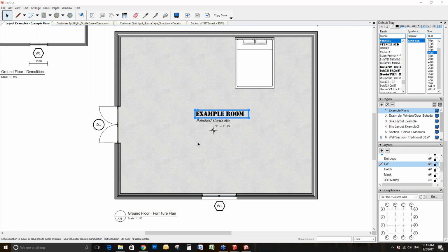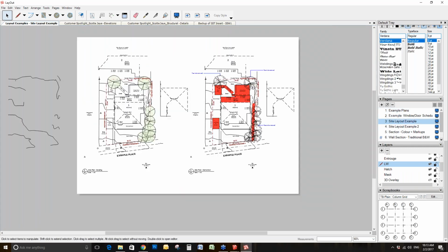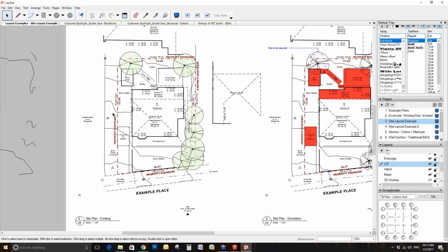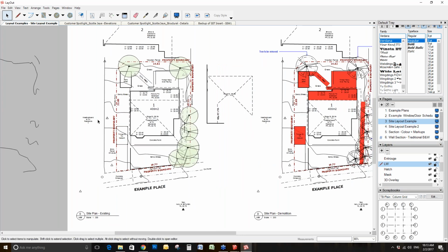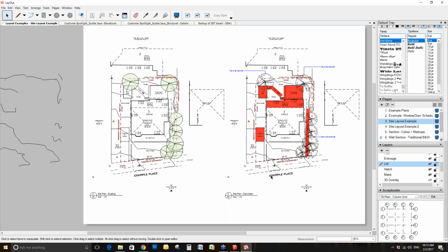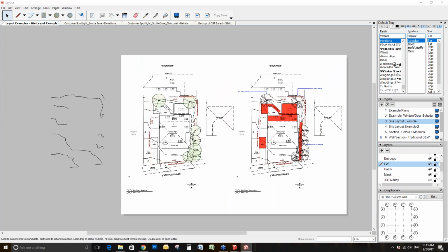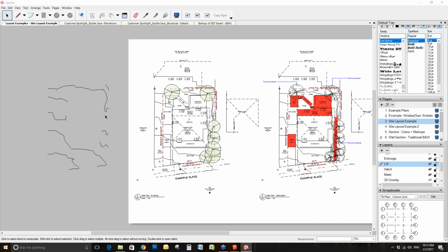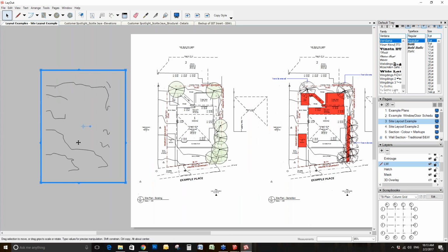There is something that's worth noting, and that is in your site plans. Your symbols often won't come through from your DWG format. There's a problem with the way that SketchUp reads the DWG blocks sometimes. So maybe just try to explode your DWG, completely explode all your blocks, and then you should be able to bring in your symbols and even your text. But unfortunately, SketchUp doesn't read the text very well from DWG.